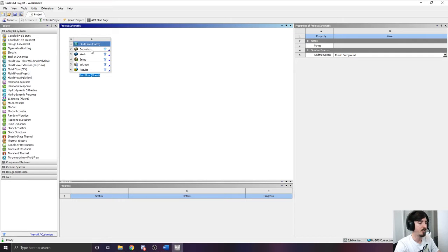Poiseuille flow is a flow due to a pressure gradient. So we're going to be taking a velocity at the inlet and showing that as it moves through a rectangular cross section. Couette flow is going to be the same rectangular cross section, but instead of a velocity inlet, we are going to have a pressure inlet of 0 and a pressure outlet of 0, because we don't want to show a pressure gradient, but we will have the top plate moving at a specific velocity and have no velocity of the initial fluid.